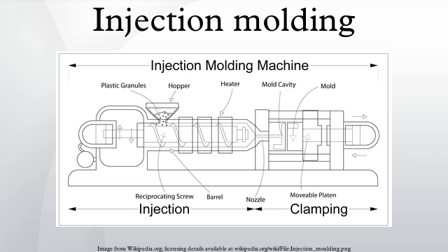When thermoplastics are molded, typically pelletized raw material is fed through a hopper into a heated barrel with a reciprocating screw. Upon entrance to the barrel, the thermal energy increases and the van der Waals forces that resist relative flow of individual chains are weakened as a result of increased space between molecules at higher thermal energy states. This reduces its viscosity, which enables the polymer to flow with the driving force of the injection unit.